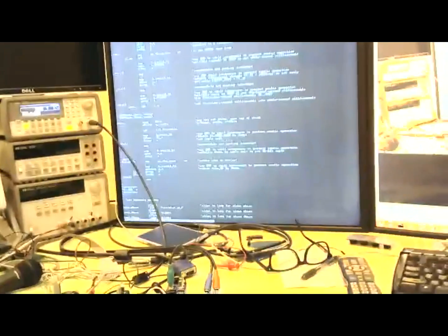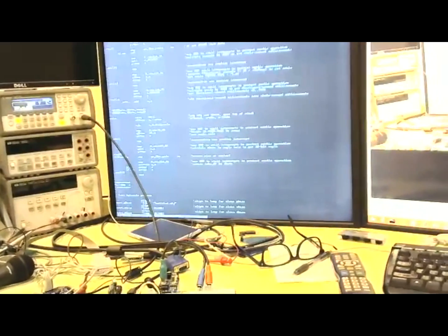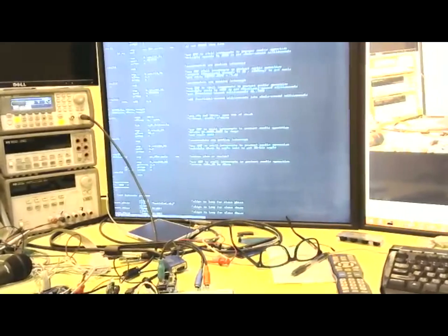That's amazing. Is the P2 fast enough to drive USB-C video? No, because the trouble with that is we start getting into LVDS running up in the gigahertz, and we don't. We could design a chip in the future to do that, but it involves making super high-speed shifters, SerDes, like are used for HDMI.